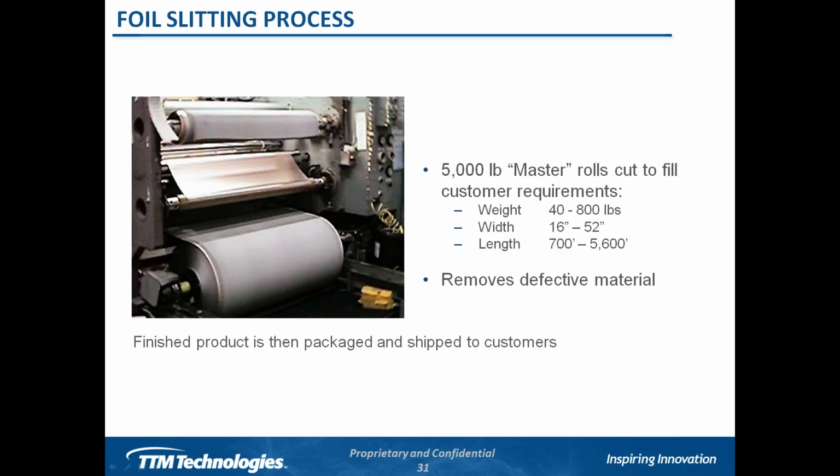And then finally, on the foil side, our foil supplier will take these large rolls of foil. Now they will cut them and sell them to us as foil only, and we're going to take these foils and do our external layer press when we build the circuit boards. But they're also going to take these foils and send them to our material supplier for them to create cores for us as well.